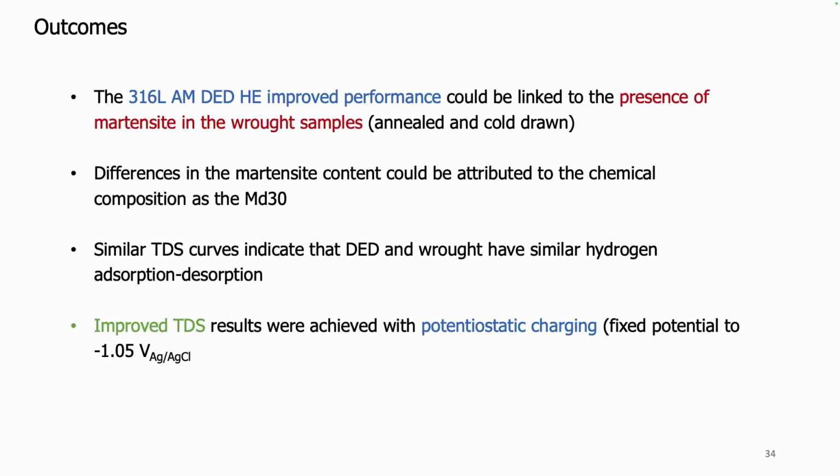And as a technical side note, we think that because we're charging for 4 days at 80 degrees, and we have a lot of surface compared to the volume, we improved the results by potentiostatic charging. Then for future work, we would like to get those threshold values and complete the experimental matrix.